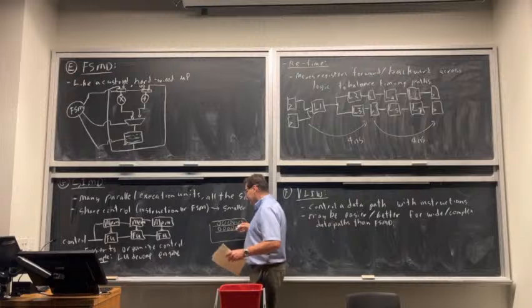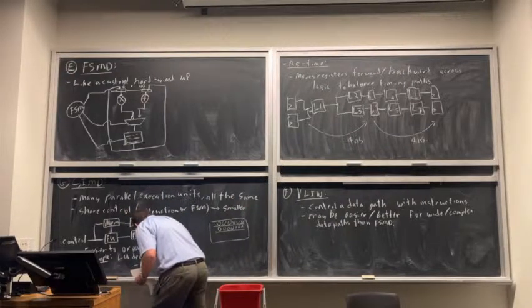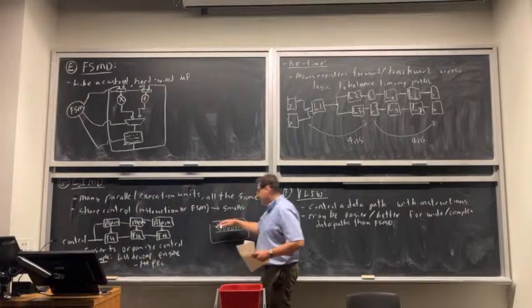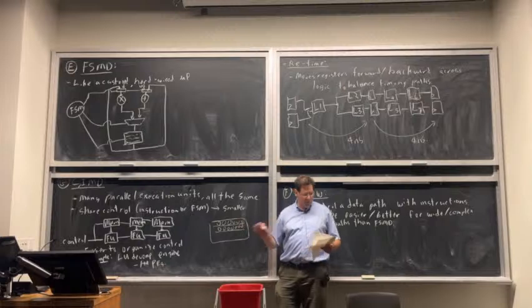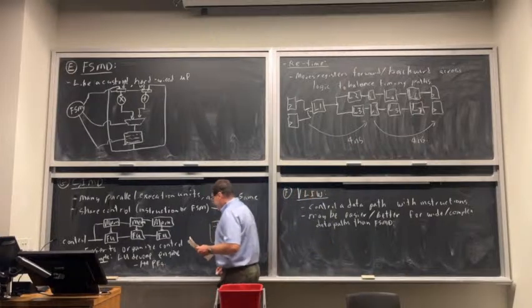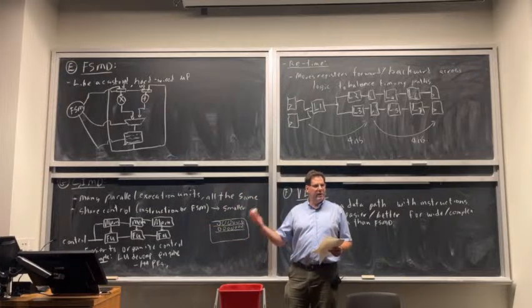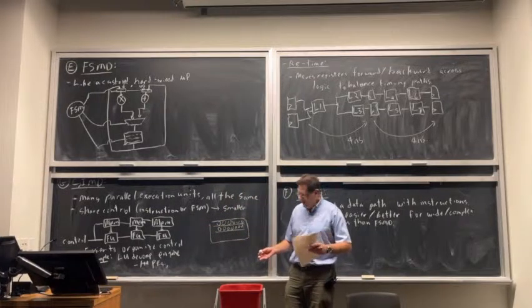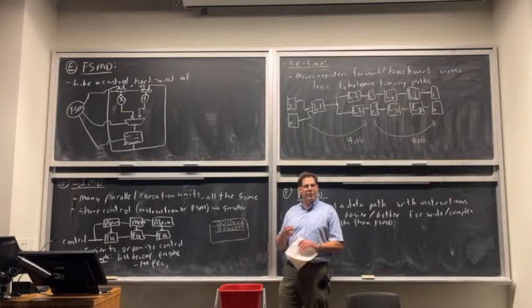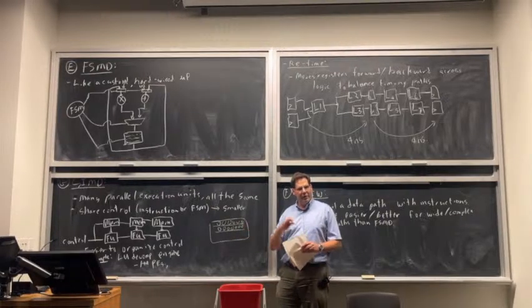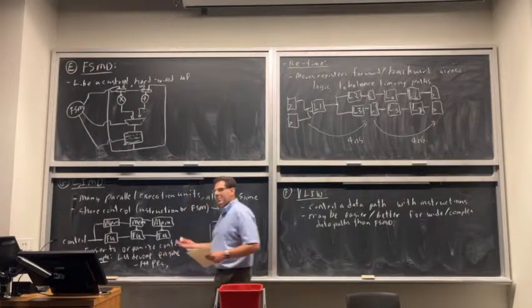And we basically built 144 of these processing elements that basically could do some operations of, subtract this from that and a few other things. So that was more efficient because we only needed one copy of the control logic instead of 144. Sometimes, if the matrix wasn't divisible by 144 columns, you're going to wind up with some inefficiency, so you lose something.